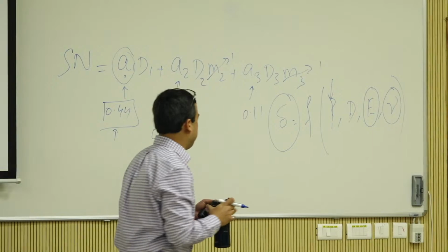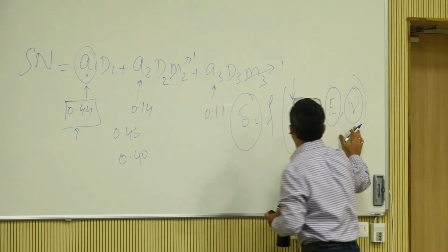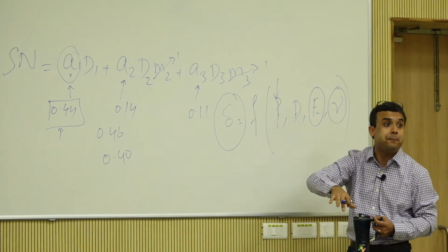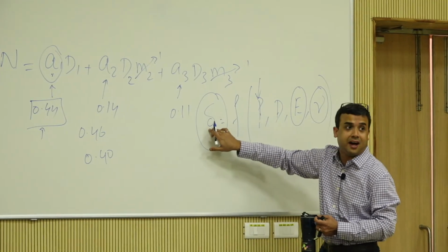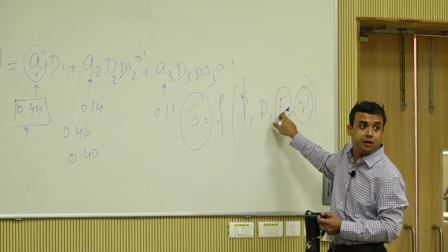This is forward calculation right now. Delta is equal to this, is that. So if you have an existing pavement and you are measuring delta, then it becomes back calculation to determine E.